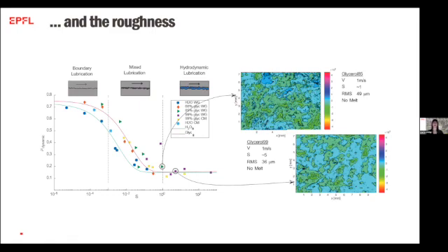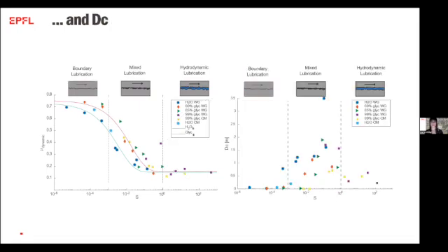So really, when we have a lubricant in between full surfaces, we can depict the behavior of the fault in terms of friction with the elastohydrodynamic theory, and this follows a Stribeck curve, with a dynamic friction coefficient going from a Byerlee friction coefficient to a friction coefficient of a lubricant.